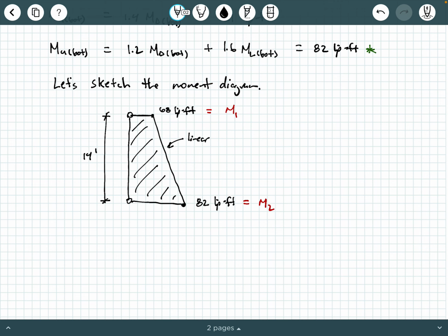Let's go ahead and get the strengths now. So let's reference the AISC 15th edition Steel Manual, Chapter 6 or Part 6, on combined loading, all right? And so what I'm going to do is enter Table 6-2.